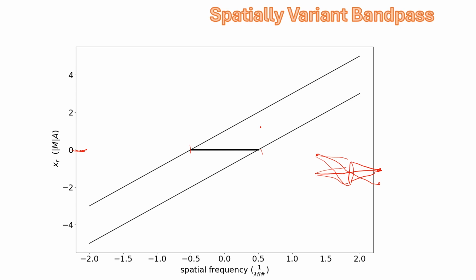So over here, the bandpass is actually at very high frequency for the actual image space. And if the image happens to be a DC image, like a plane wave, then you'll get cut off. Out here, the DC component is just not getting through the lens. Now, we don't see this often when we look at natural images. If you have a white wall and illuminate it, you'll see a white wall in the image space.